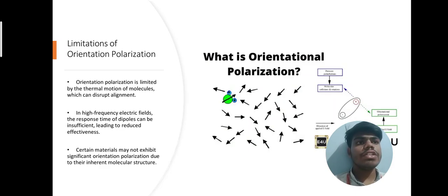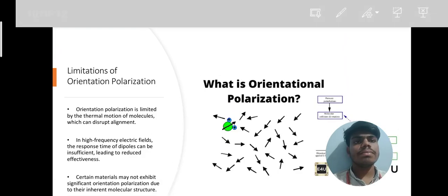Limitations of orientation polarization. Orientation polarization is limited by the thermal motion of molecules, which can disrupt alignment. In high frequency dielectric materials, the response time of dipoles can be insufficient, leading to reduced effectiveness. Certain materials may not exhibit significant orientation polarization due to their inherent molecular structure.